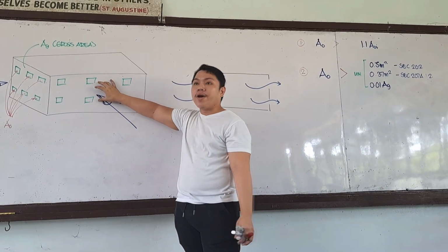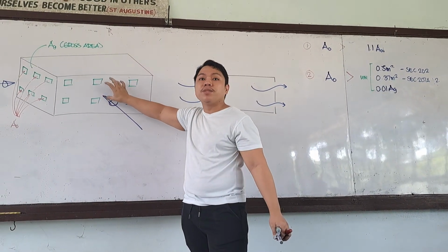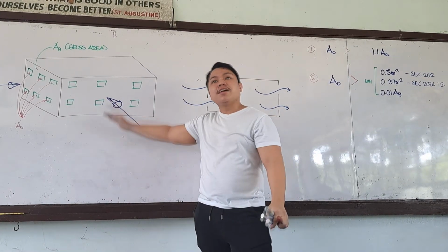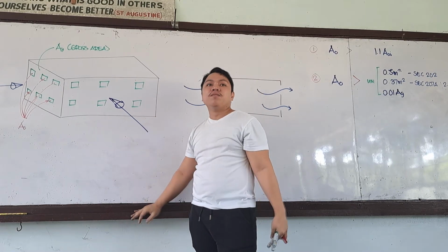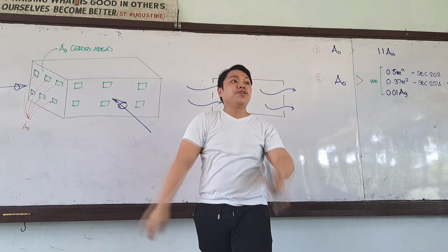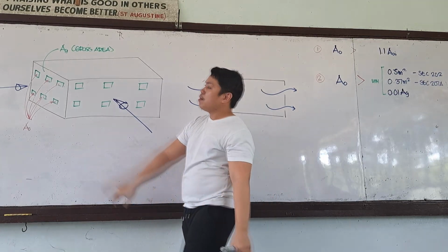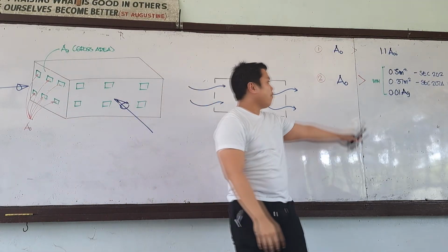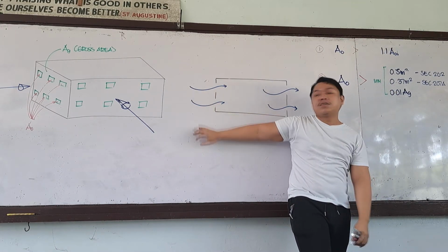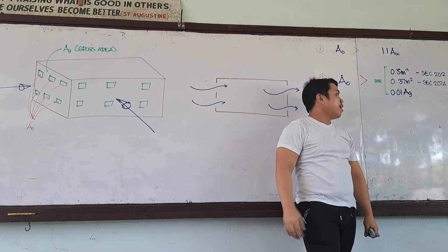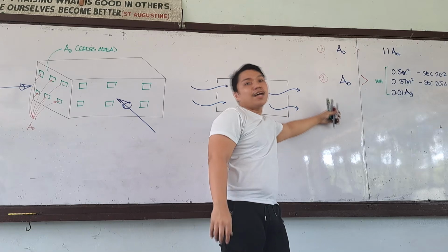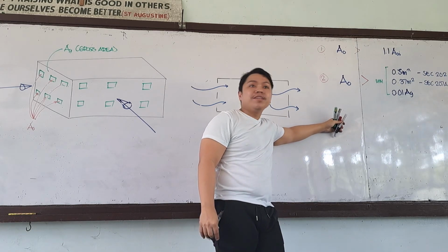The consideration for open is that no internal wind pressure remains inside: when wind enters, it goes straight out through the remaining walls. For partially enclosed, when wind enters, it depends on the areas of the remaining sides of the building envelope. And if we do not meet both conditions for partially enclosed, that is an enclosed building.